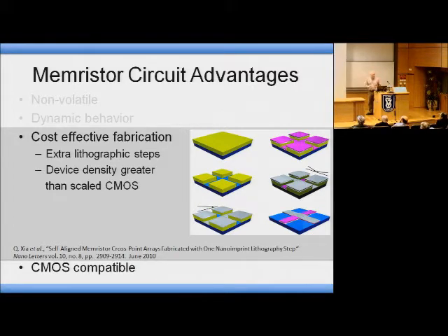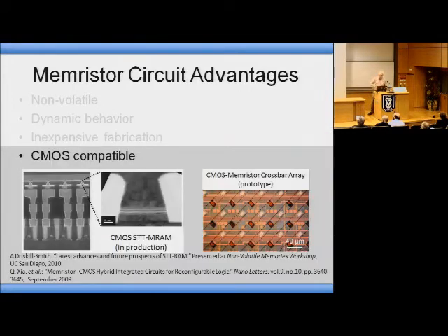It makes it interesting. And so, not just on a circuit level, but actually even on an architectural level, you can do new things about how you want to blend these classical CMOS technologies merged with this MTJ technology. So it's interesting. Again, there's a whole family, important work being done in material development. This talk is intended just to review some ideas and thoughts at the circuits level, specifically the STT, which I'll explain in a second why I care. And CMOS compatibility, here are some nice pictures showing compatibility, STT being built right above the CMOS plane.